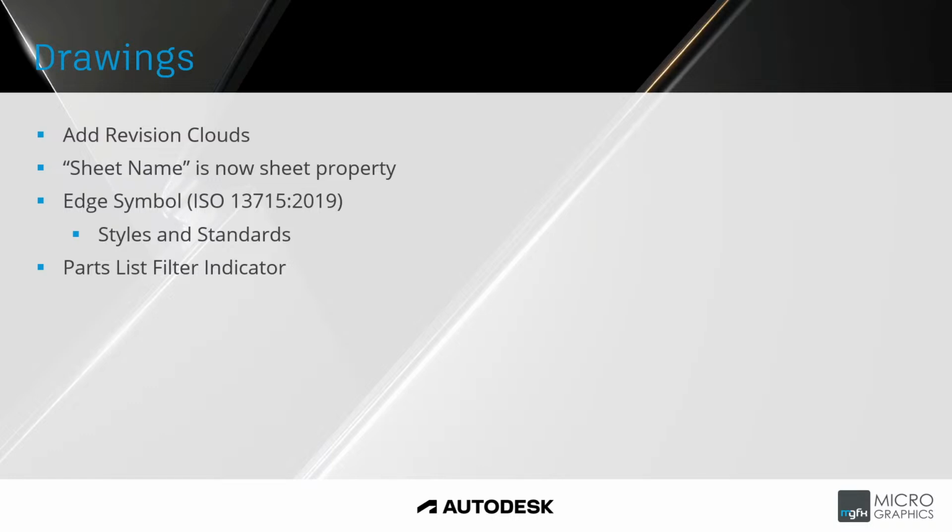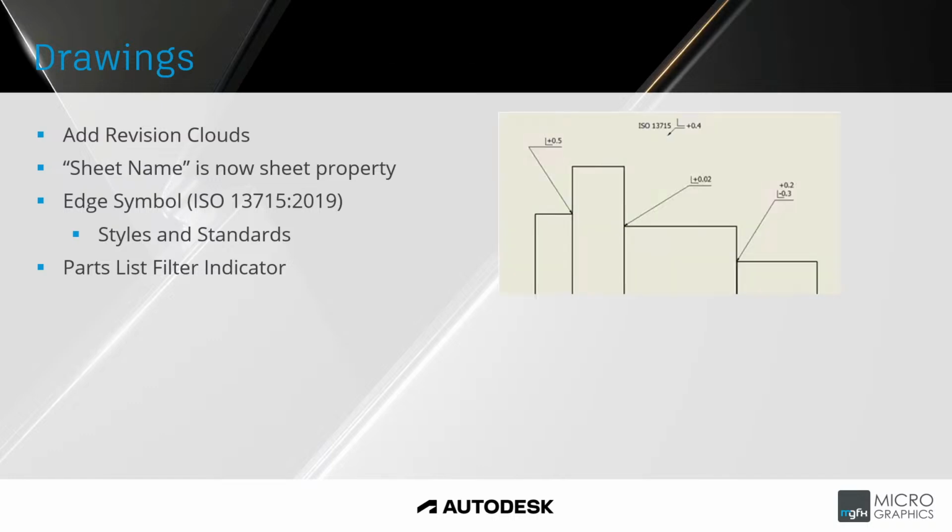We also now have the ability to add the sheet name into the drawing because it is now a sheet property. So in your title block or in a note, you can add the sheet name as a property to update and display on your drawing. There's a new edge symbol that's been included in your styles and standards, your symbols, where you can insert your symbols, and that is bringing in line the edge symbol. That edge symbol aligns with the ISO 13715 standard. So you can see here on the right hand side, we've got the edge symbol there with the various information linked to that.